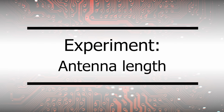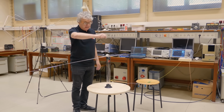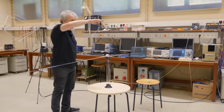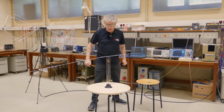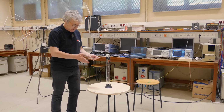Now let's think about the current on the antenna. This is extended as a dipole now, and at the lowest frequency, the current would be sinusoidal, has to be 0 at the ends. Here, of course, there's no metal, so a sinusoidal current cannot flow. This would be the first resonant, lambda half. Now, think about if we reduce the length of one side.